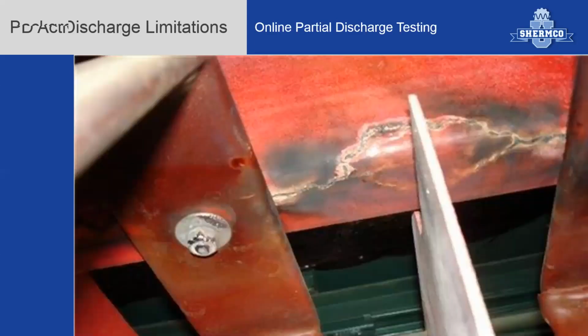Okay, and in conclusion, let's talk a little bit about limitations. Although online partial discharge testing is a wonderful tool, again, I caution it does take knowledge and experience, understanding of how the sensors and the technology works, and an understanding and knowledge of the type of insulation that we're studying. There are situations where even with online PD studies, a fault occurs.